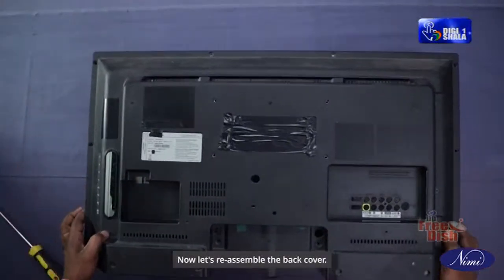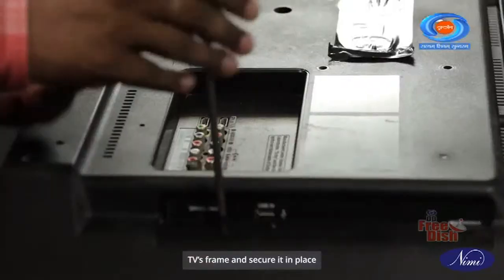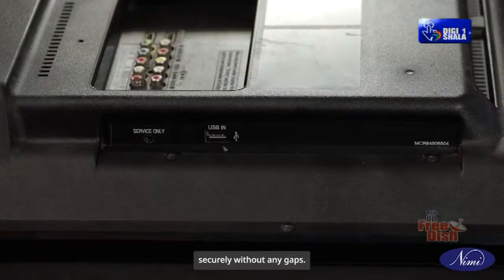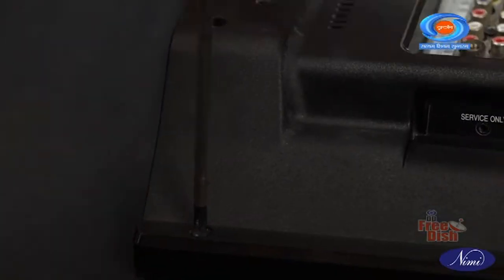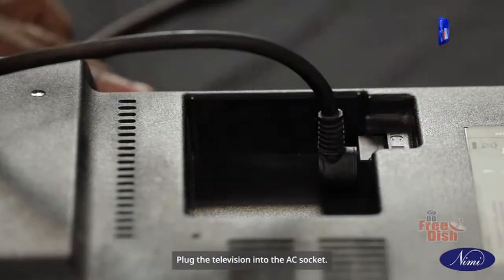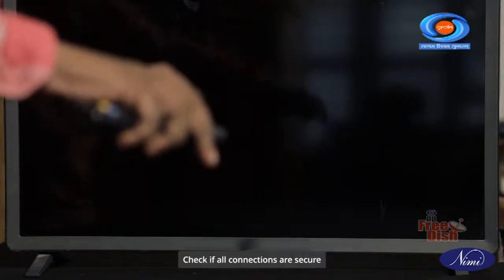Now let's reassemble the back cover. Carefully align the back cover with the TV's frame and secure it in place by tightening the screws. Ensure the cover is fitted securely without any gaps. Plug the television into the AC socket. Switch on the TV using remote. Check if all connections are secure and that the devices are receiving power.